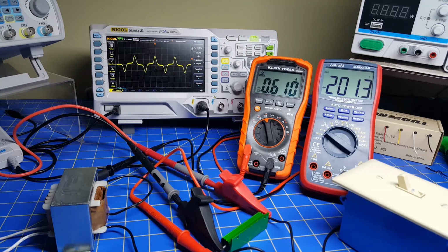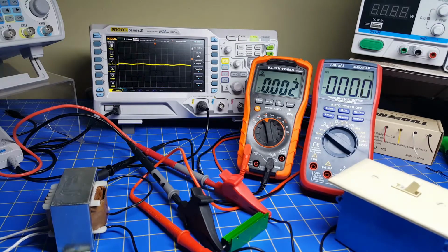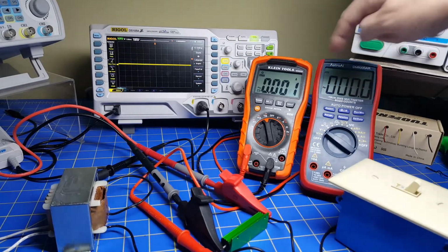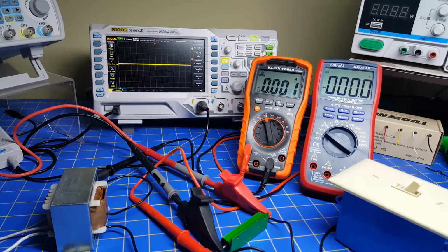And you may be able to hear the transformer humming because of the harmonics flowing. And I'm going to go up, and I'm up to 220, and I'm going to stop there. I'm over 1 amp. So that gives you an idea, and if we play this back, we can see the relative current and voltage. But you can see you're getting over an amp with 220 volts, and it's going to turn out that this is quite a bit different from what we assumed. So what we'll do is we'll go back and grab that data from the video and plot the curve and see where it puts us.